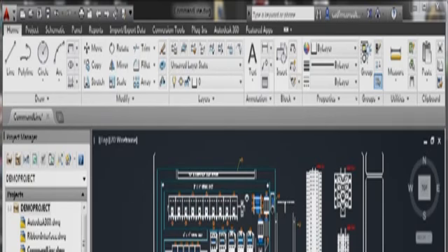Input search options. If I click on that, I can go in and set all of my search options for the command line. I've got autocorrect on and off, remember corrections, list delay time, 300 milliseconds, everything. I can set everything I want alphabetically, frequency. It's quite an incredible setup now, and it's been thought about in depth by Autodesk to make the command line a very valid tool while you're using AutoCAD.